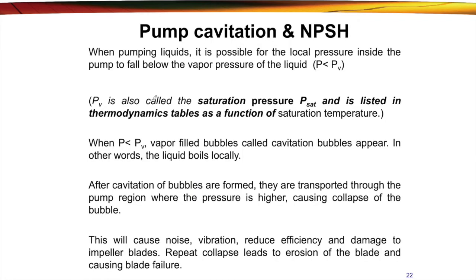Okay, so now we move to pump cavitation, or NPSH. When pumping liquids, it is possible for the local pressure inside the pump to fall below the vapor pressure of the liquid. So the pressure in the pump is below PV. Before that, PV is the saturation pressure. So what will happen when the local pressure of the pump is below the saturation pressure? It will create bubbles.